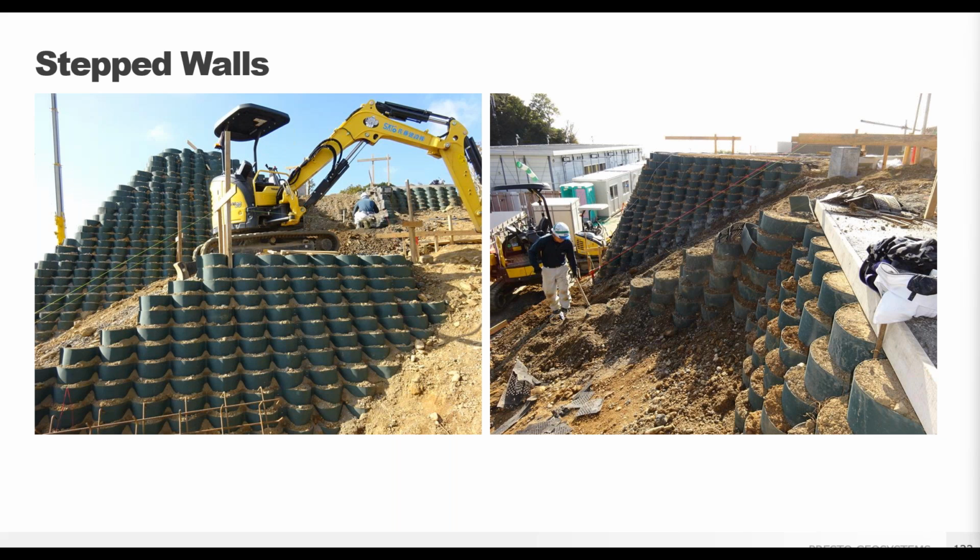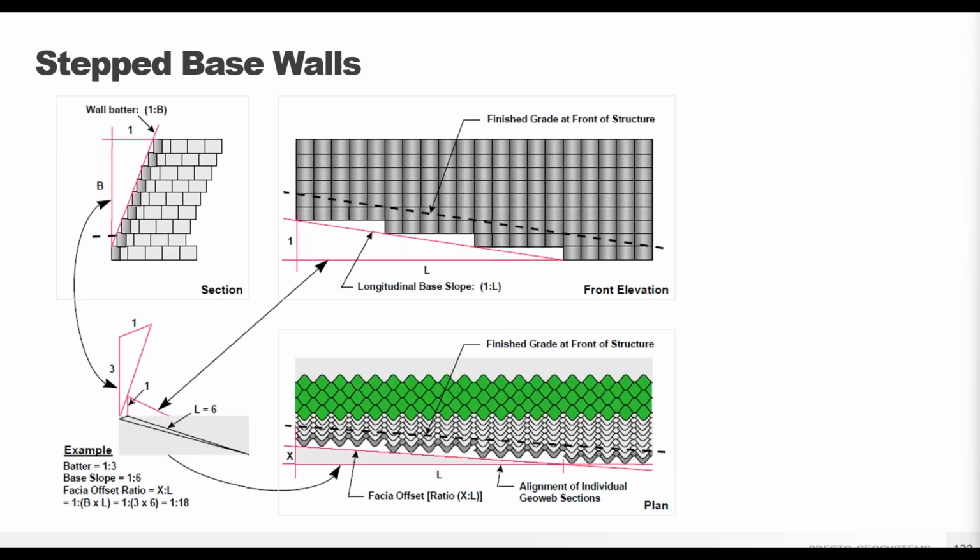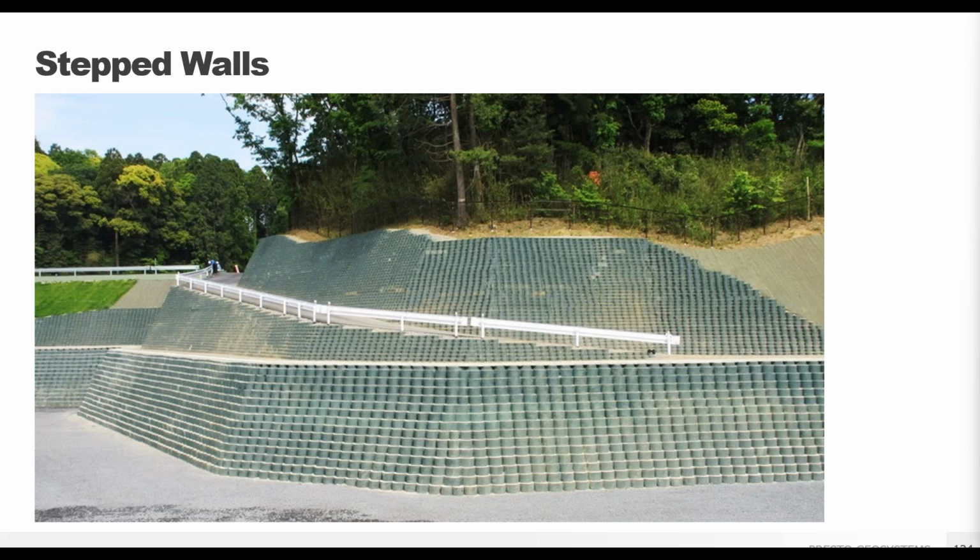Stepped walls are a bit of an advanced installation, needing some technique and extra planning. Our full installation guide gives examples of calculating offset dimensions for a GeoWeb wall on a stepped base, and you should be sure to coordinate with our in-house engineering team for some additional guidance. Stepped walls can be useful for an interesting wall such as this, where the engineer used 3 different wall batters and multiple stepped areas to make GeoWeb fit the site conditions.